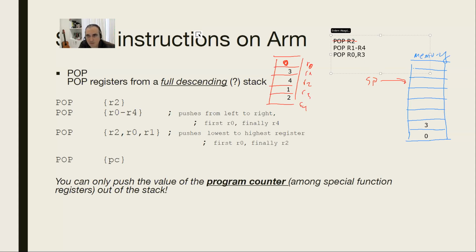Okay, to here now, and stack pointer. So, and I have this instruction also gone. That's how you do it, guys. I'm not going to be continuing. So if this is R0, R3, in commas, the lowest register first. So 3 will be written into R0 because R0 has the lower index, and 0 will be written into R3. So guys, this is how you do it. This is the structure. Did everybody get it?